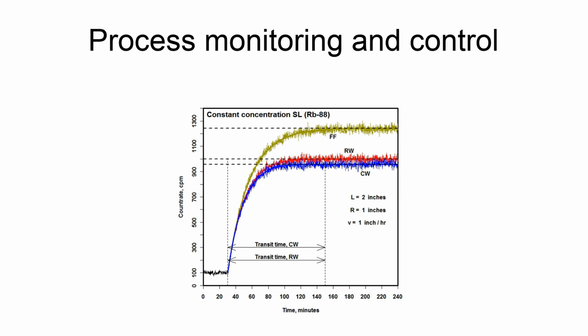A control room shall be provided from which actions can be taken to operate the nuclear power unit safely under normal conditions and to maintain it in a safe condition under accident conditions, including loss of coolant accidents. Adequate radiation protection shall be provided to permit access and occupancy of the control room under accident conditions without personnel receiving radiation exposures in excess of 5 rem whole body, or its equivalent to any part of the body, for the duration of the accident.